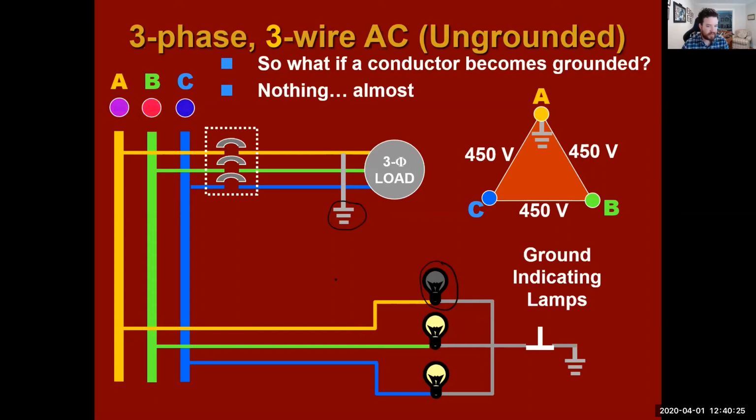And what is physically happening is, like we said in the beginning of this class, this ground here is attached to this ground. You might as well have a wire connecting both of those. So what is happening is that you have 450 volts coming in on both directions here, and you have 450 volts coming here. But the big difference is that these are in the same phase, so they cancel each other out. This light bulb will never light because they are canceling each other.